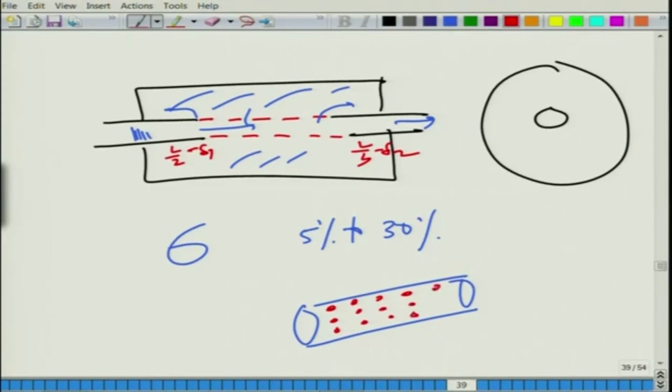There have been different manners in which perforated things are drilled. Through these holes, the waves are allowed to interact with the outer cavity. So, if this is 30%, then it is highly porous, it is virtually acoustically transparent, but at the same time mechanically it is allowing the flow to go through. These holes are very small, roughly 2 to 4 mm in diameter, placed at a certain spacing. We see these perforated things very commonly. I will show you some photographs of the perforated parts that we made some time back.